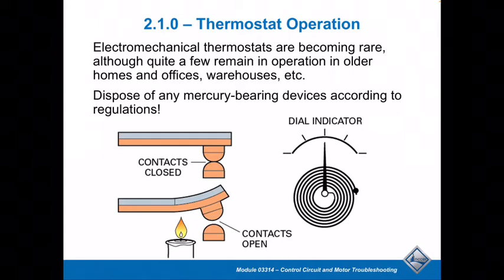Now, specifically, there are different types of thermostats. You can have more mechanical type thermostats, and you can have thermostats that are electronic. The mechanical thermostats would usually use some sort of bimetal that might incorporate a metal like copper or brass, and then possibly Invar as another metal, which is about 35-36% nickel, and they fuse these two metals together.